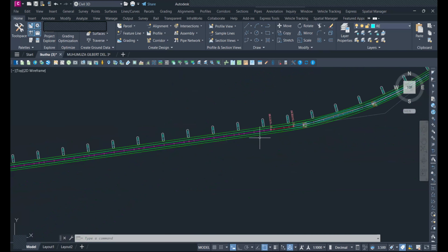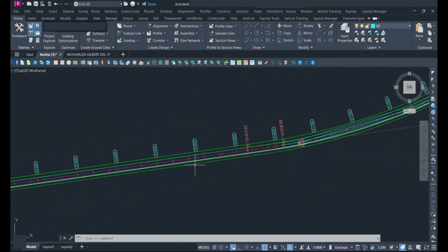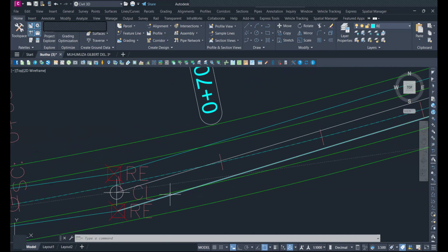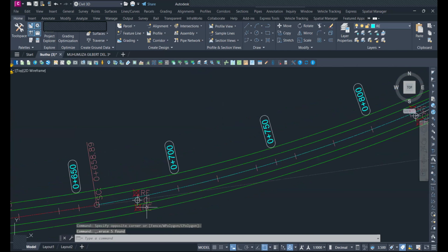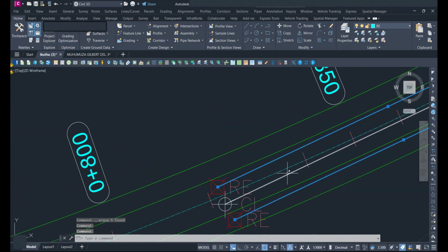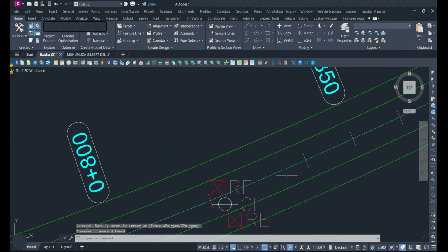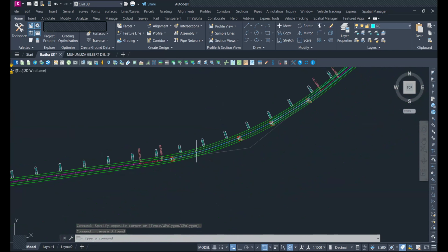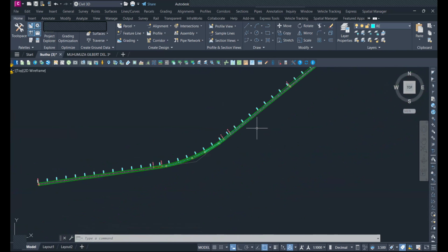Now, I noted something that I went and asked to correct. The horizontal alignment is good. Actually, what I was doing, I'm deleting these polylines, because now once we have already been able to establish our best alignment, we just don't need all of these points. These lines that were for the existing route. You can just do away with them, and you are basically left with your road project as it is here,